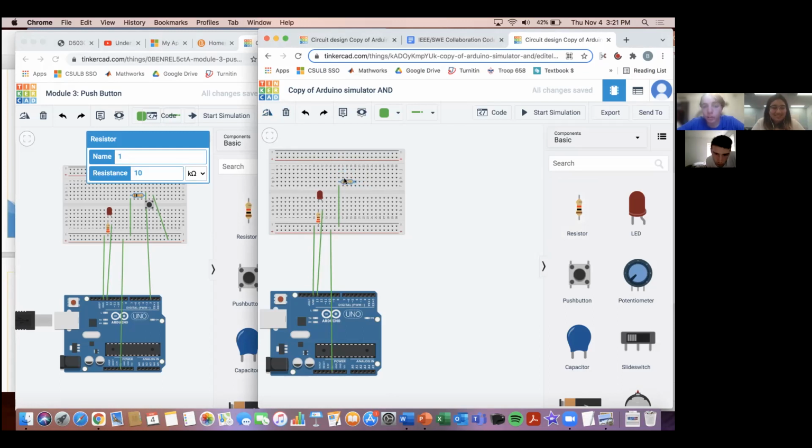And now I'm going to hook up the push button. So a push button, you guys need to get a little familiar with, so I'm going to draw it out here. What a push button does is it has 2 terminals here, and it has another 2 terminals on this side. So it has terminals on both sides. And what's the interesting part is that 2 of them are interconnected to the button.